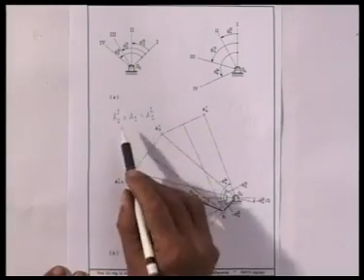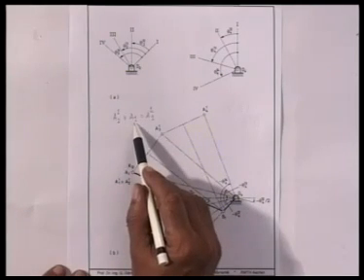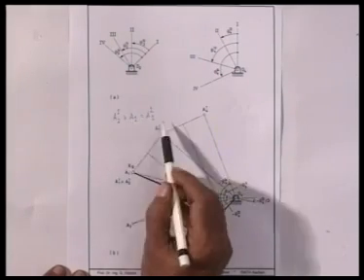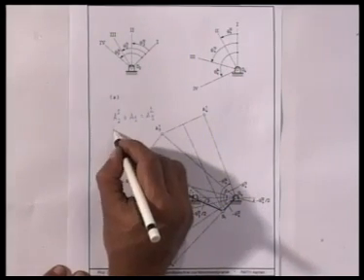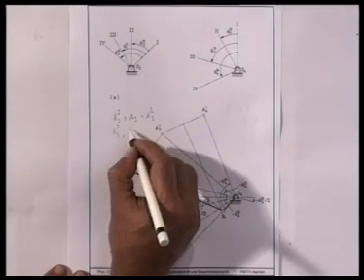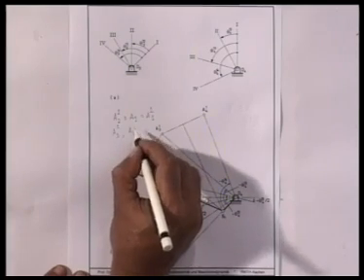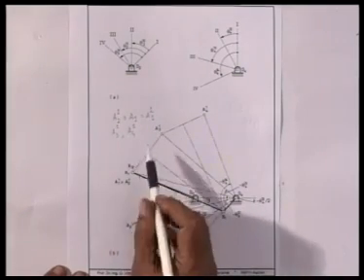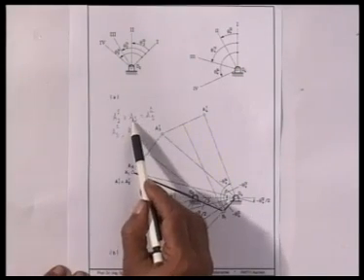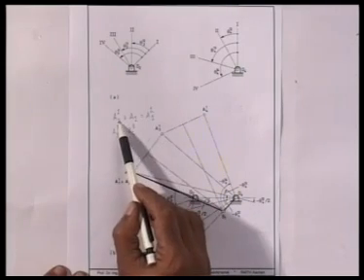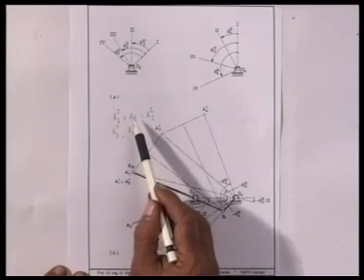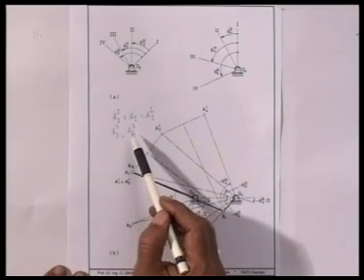I will explain how to obtain this such that A21 coincides with A1. The choice of A1 is guided by this. Once after this, I can always obtain A31 and A41. So two of the inverted positions are the same, so I get three distinct locations for the inverted positions of A, namely A11, A21, A31, A41. Then I can determine the center of the circle passing through these 3 points and get the location of B1.